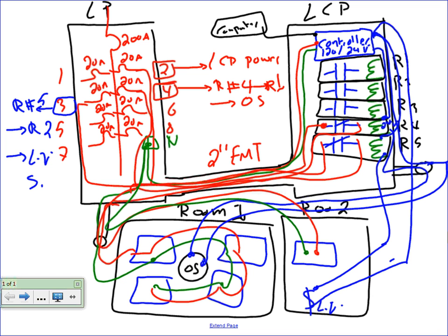Anybody can tell me what type of wire can I use for the 24 volt here? Class 2 wiring. Absolutely. Can I use the HHL? Yeah, but you can, it's class 2 wiring. 24 volt, power limited, control, low voltage limited.